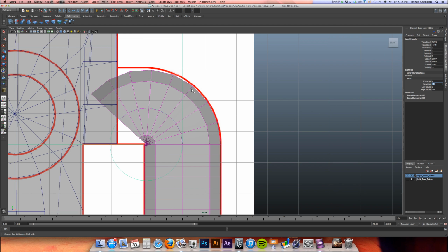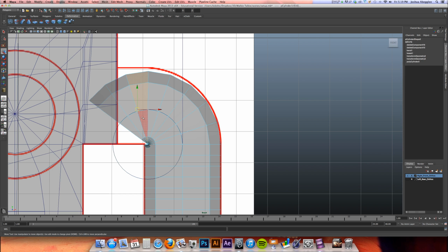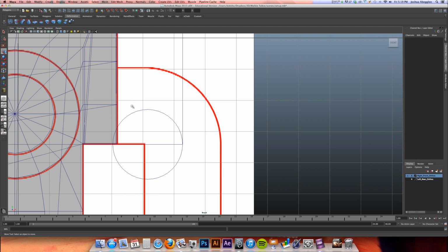All right, I want to at least have one edge that represents an approximate 90-degree angle right here. All right, so let's try -6.5. That looks like that is too much. Let's try -6.25. Looks like that is pretty close. Let's come in here and delete these additional faces. Oops.